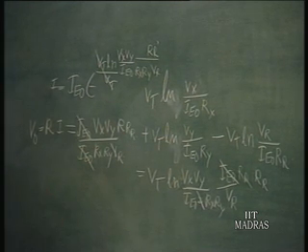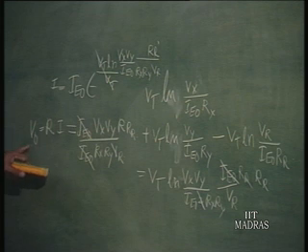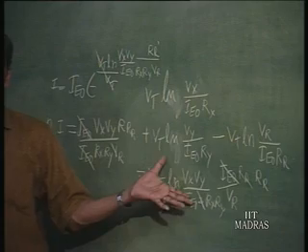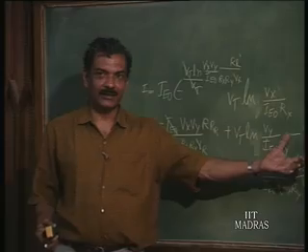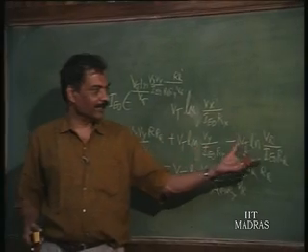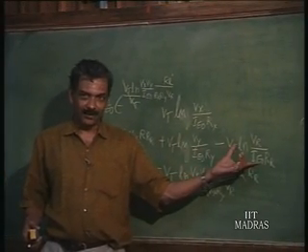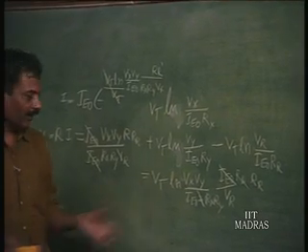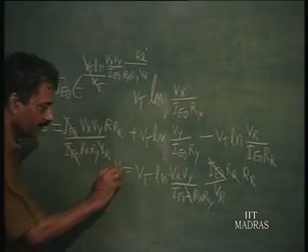So, you therefore get an output voltage which is independent of the effect of IE naught as well as Vt. So, when we design a multiplier, we can simply take log amplifiers, add the diode voltages, subtract this reference log, and then take the anti-log of this effective diode voltage.